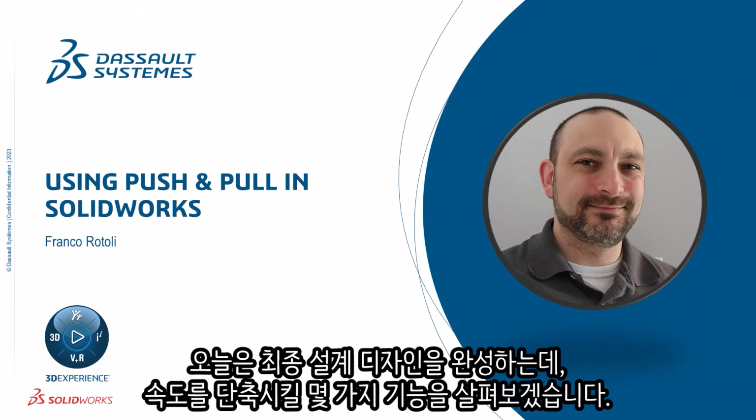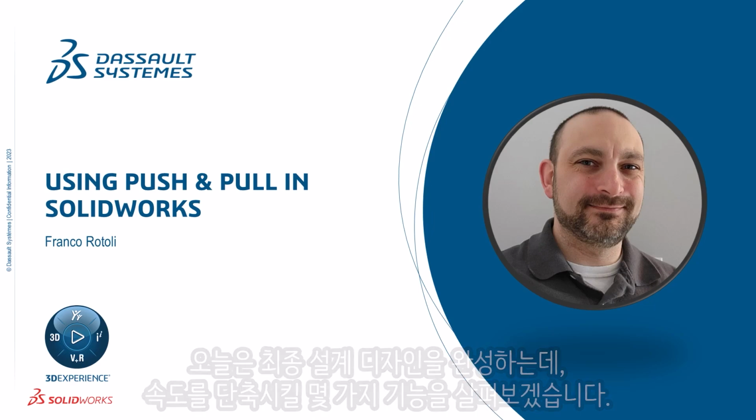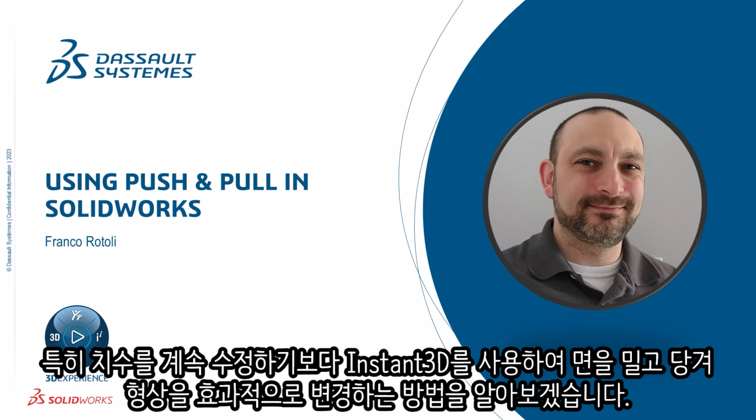Today, we're going to look at some helpful tools to speed up our rough concepts and get them to a final design. Specifically, we're going to use Instant 3D to push and pull faces to change our geometry, rather than modifying dimensions over and over again.